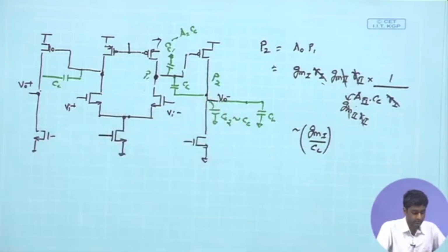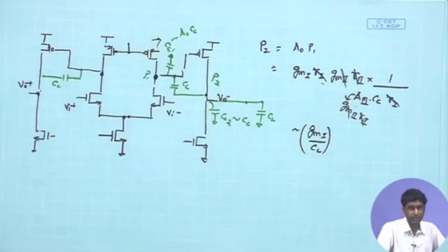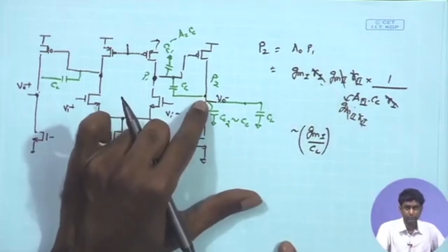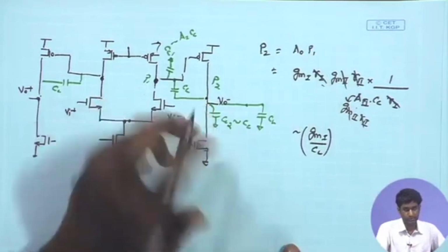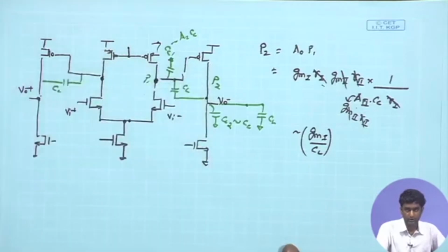Now, the other question is, what is the R equivalent at this point, that is, what is the small signal resistance at this point. If I look at low frequencies, definitely for writing the gain we have used the overall R equivalent at this point equal to the RO of P parallel RO of N, that is giving us RO by 2.